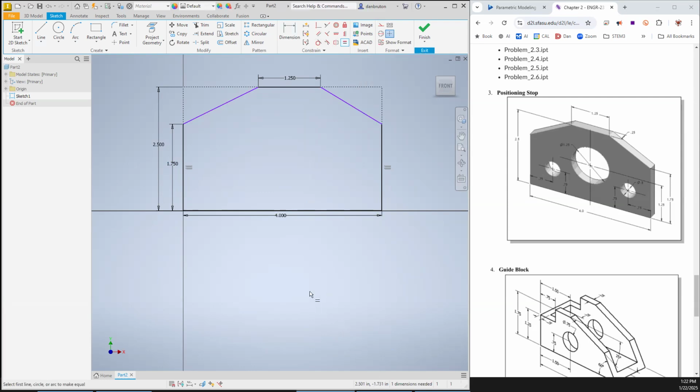So let's see, what are some possible things that we can do here? I guess what we can do is make these two links equal, and that will probably constrain everything that we need. So if we click here and there with a shift click or a control click, I think it's control click actually. So click and then control click, and it says already constrained. Oh, great. So it looks like I already made it equal. Let me undo that. So I actually clicked on the equal sign. I was still there, and I want to make those two equal. And look at that. It's fully constrained.